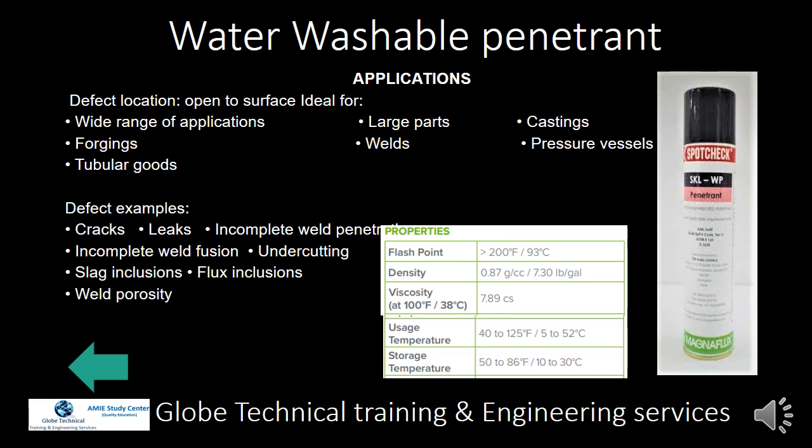The flash point of this penetrant is 200 degrees Fahrenheit or 93 degrees Celsius. Applicable temperature for use is 5 degrees Celsius to 52 degrees Celsius. Also store this penetrant at 10 to 30 degrees Celsius.